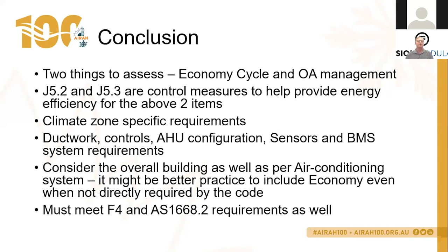So if you have a situation where you have calculated that it's not more energy efficient to provide the heat exchanger, and you've got all your calculations and you can determine that it's not more energy efficient, then that would be your performance-based solution for excluding the heat exchange and not meeting that code compliance requirement. And that would be it. So you would therefore just have some calculations that demonstrate that your performance-based solution says I don't need a heat exchanger because it's less energy efficient. If that makes sense.